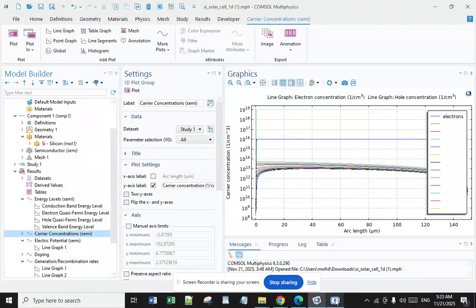The central semiconductor parameters that determine the design and performance of a solar cell are, first, concentrations of doping atoms, which can be of two different types: donor atoms, which donate free electrons, Nd, or acceptor atoms, which accept electrons, Na. The concentration determines the width of the space charge region of a junction.